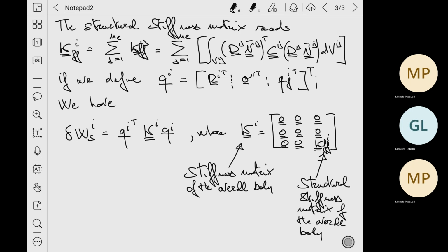Okay, can you figure out why that would be? I give you a hint on this. It's basically because your point of view on motion does not follow your body in the absolute nodal formulation, because you basically describe all of the motion straightforwardly from the inertial frame.